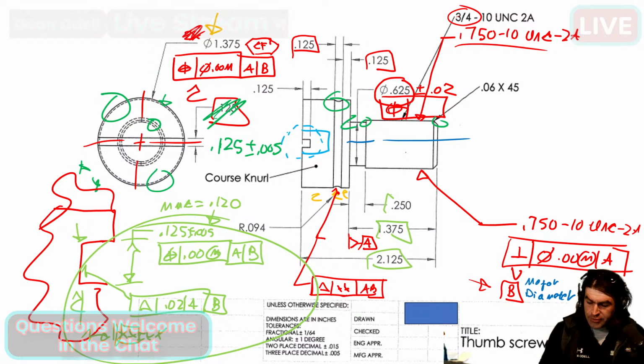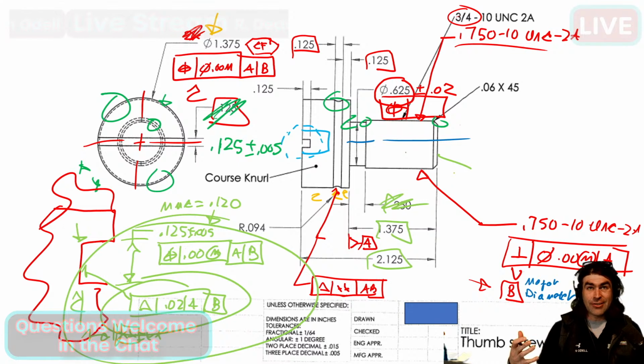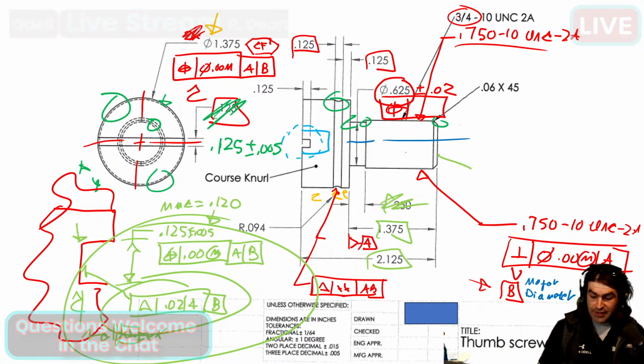These locational dimensions, probably not that one. We would just use profile, right? No big deal to locate those surfaces, just like I was complaining about right here. It's easier on these surfaces though, because they're external. So, not too big of a deal there.